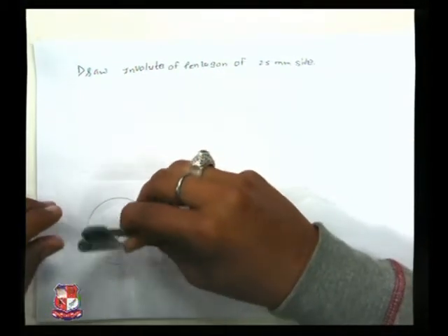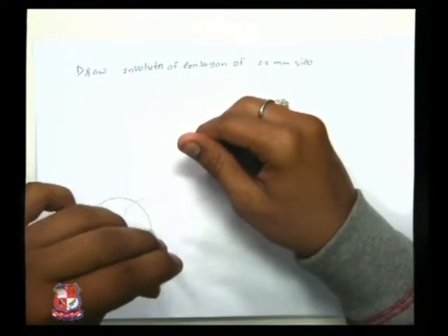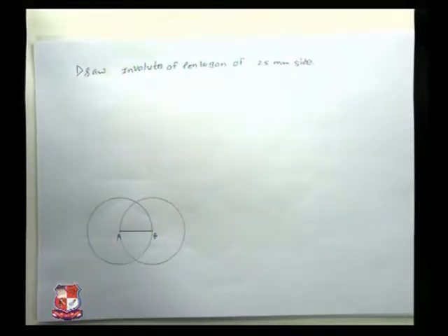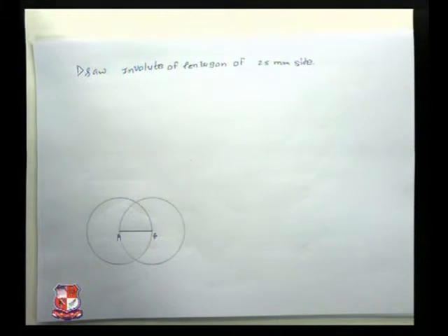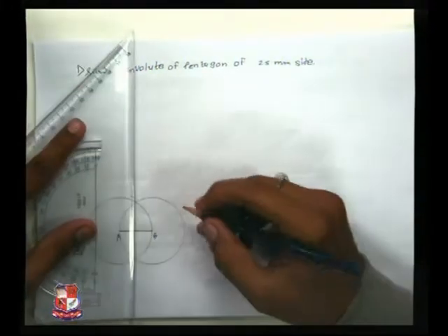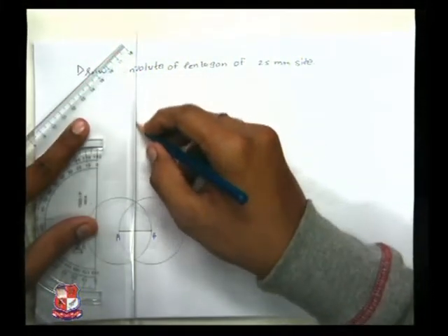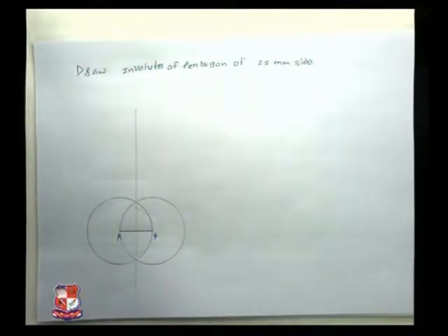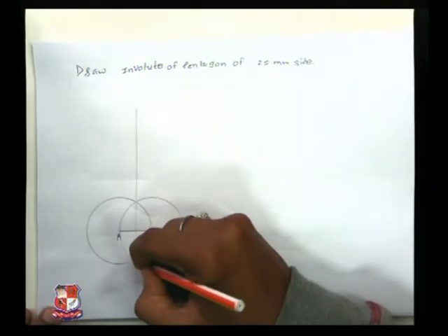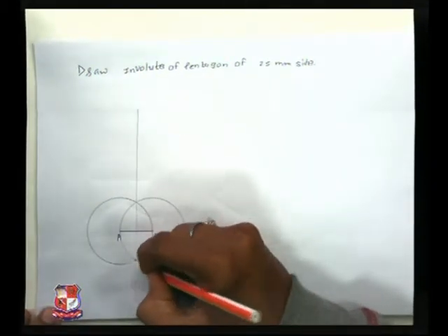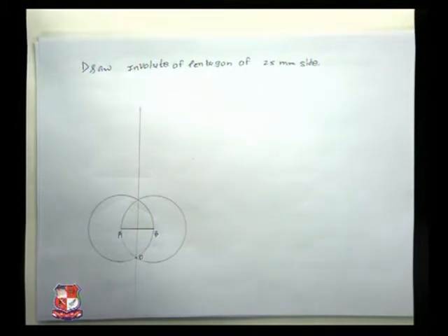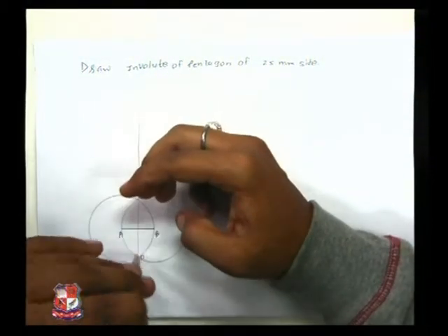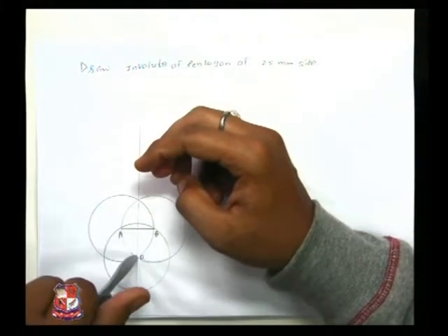The name of the method is the 3-circle method. So the third circle is missing. Now we have got the bisector by default. Now from the lower portion, let's call it O. O to B as radius, and draw the third circle.